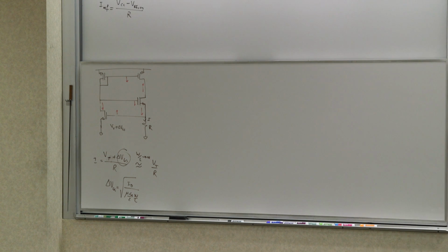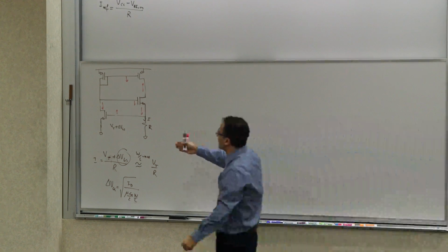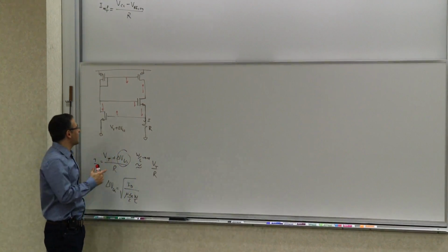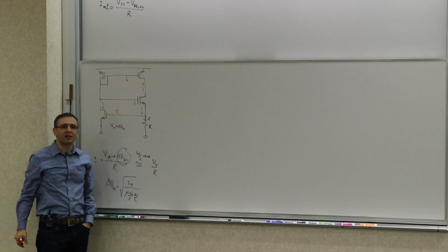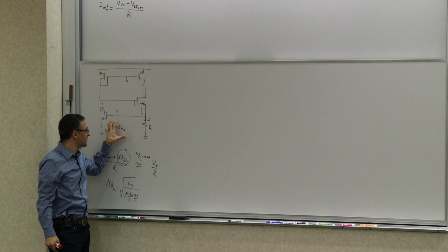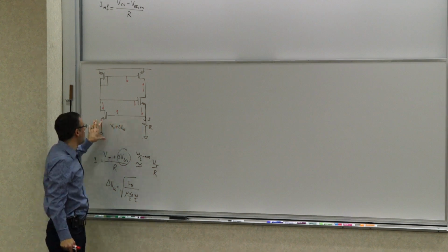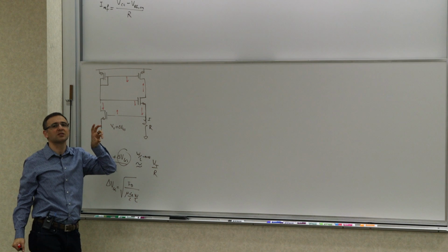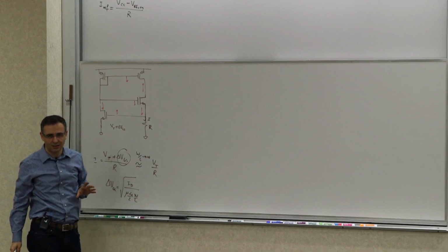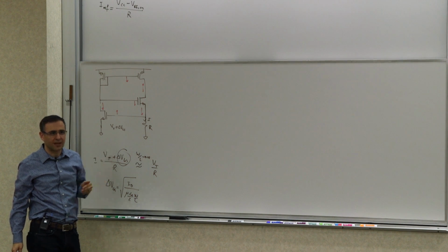It has another problem. The problem right now is that it's not dropping the delta VGS, so it's an approximation. Now, in general, there are a lot of these scenarios that you will see when you're talking about these supply voltage independent, PVT independent generations. You're trying to drop a voltage or the difference of two voltages across a resistor and turn that into a current. And we'll see more examples of that as we go.